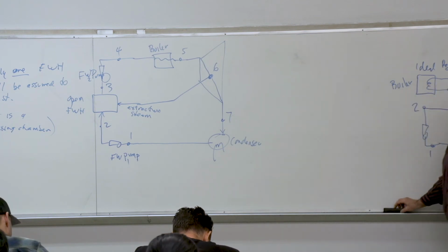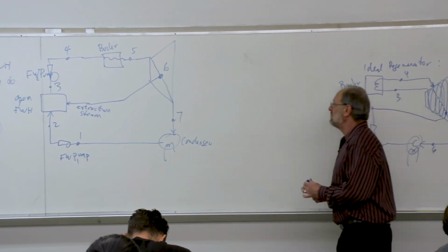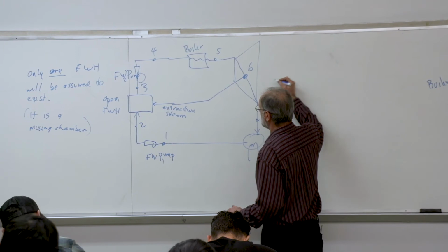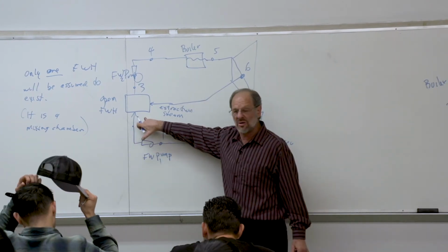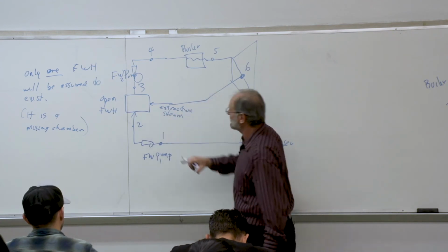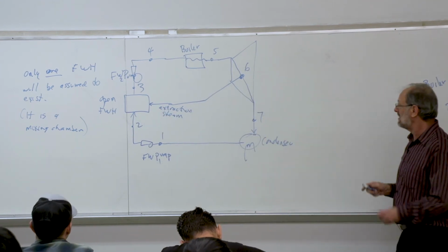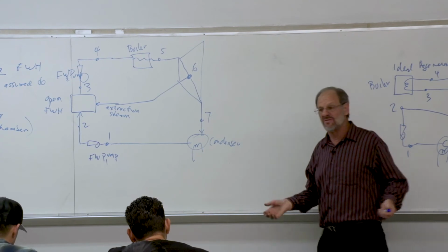All right, so this is the basic process. Please note that the pressure of the feed water entering the feed water heater and the pressure of the extraction steam have to be the same. Okay, if they're not the same, then you have flow problems, right?